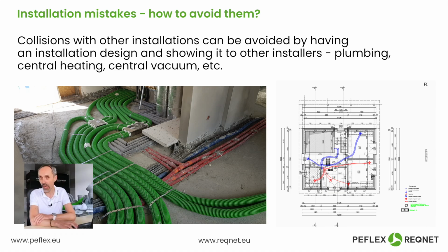This is something to avoid, meaning collisions with other installations. If we have a design, let's discuss it with other installers, with other teams, so that we can fit everything within that acoustic insulation layer on the floor.